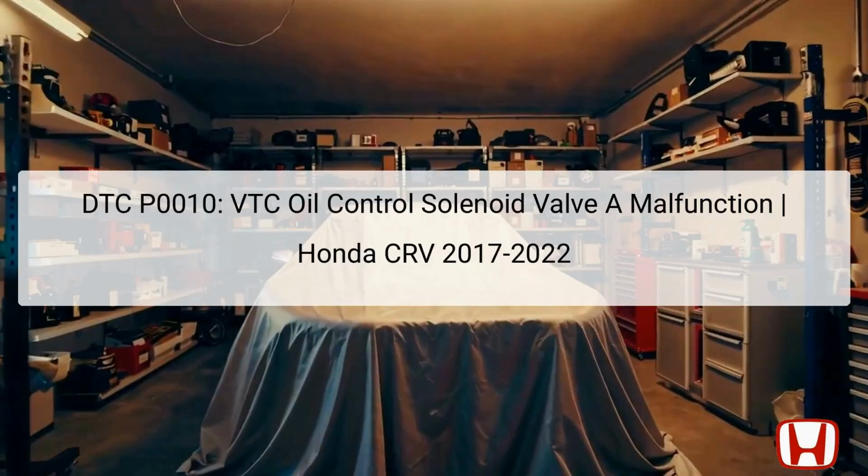The DTC P0010 indicates a malfunction in the variable timing control, VTC oil control solenoid valve A, which plays a critical role in controlling the variable valve timing in Honda CRV models from 2017 to 2022. This solenoid is responsible for regulating oil flow to the VTC system, allowing for optimal engine performance and efficiency. It's typically found near the engine's timing chain or belt, making it integral to the engine's variable timing mechanism.